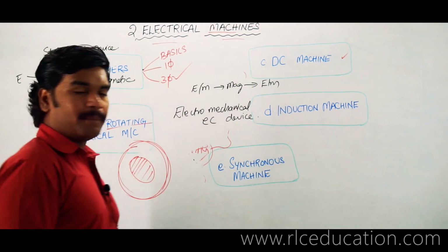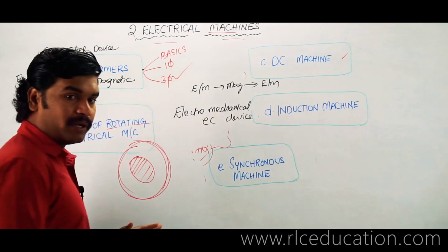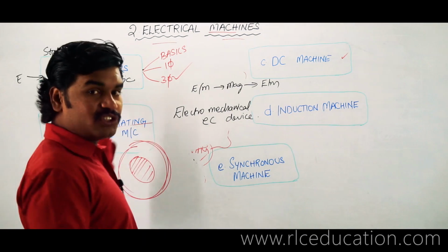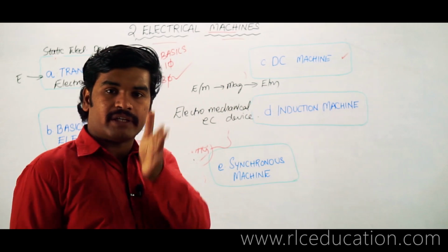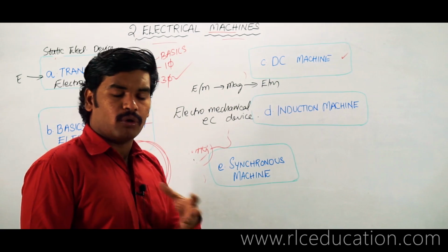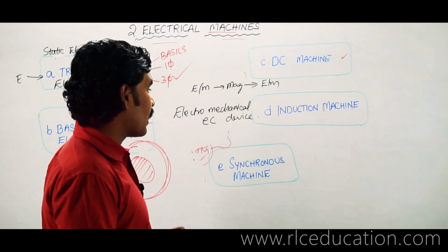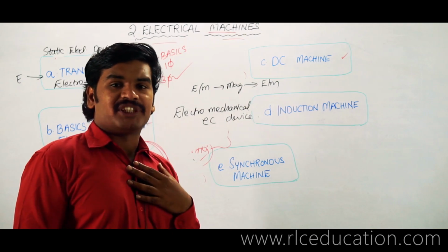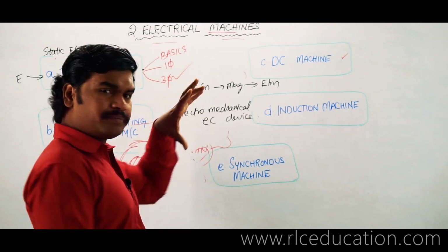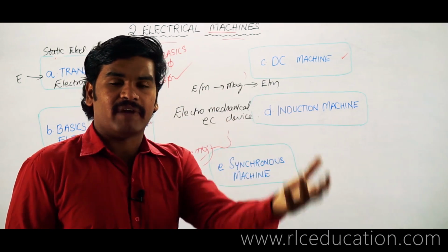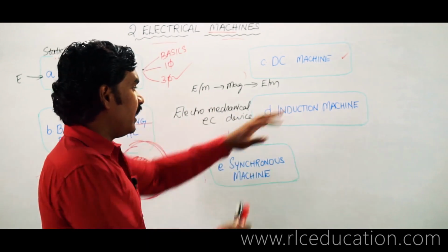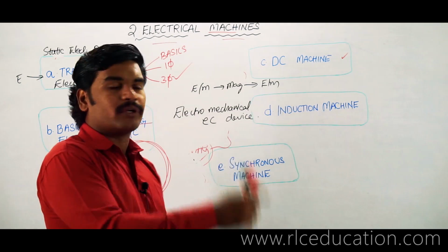But there is one common thing between an induction machine and a transformer. A transformer, as you know, is a two-winding device. It has an input winding and a secondary winding at the output end. What an induction machine has is a fixed primary winding, but the secondary winding, like the one we have in a transformer, is now on a rotating member. Now it forms a rotating part.